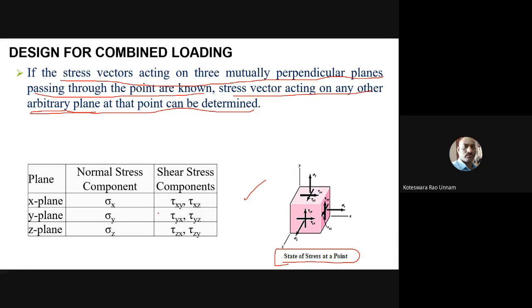Before that, I think we already discussed this notation, how we got it in the case of normal stress. It is simple. The notation is sigma x, sigma y, and sigma z. That means if the perpendicular direction to the cross section is the x direction, then the stress is also in the x direction. I'll call it a normal stress. That's why the stress direction or load direction and the perpendicular direction are the same in the case of normal stress.